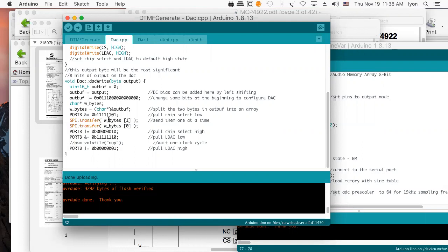But that NOP, what is that doing? It's giving you a small delay, no operation, where the CPU sits idle as you flip this bit from 0 to 1. And that is all it does. It could be useful for reading the output, right? No operation, it doesn't read anything, it doesn't write anything. It just sits there and cycles a little bit of CPU time, as when you write, you may be exceeding the time it takes to get a reaction out of the DAC.